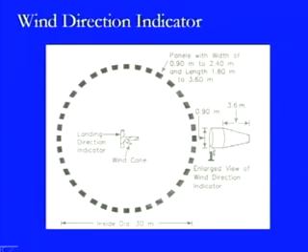There is a pole, and at the top of this pole there will be a conical surface provided, with 0.9 meter diameter at this side and 3.6 meter length of the cone. So, that is the minimum specification related to this. At the same time, the sizes of the panels are also specified.